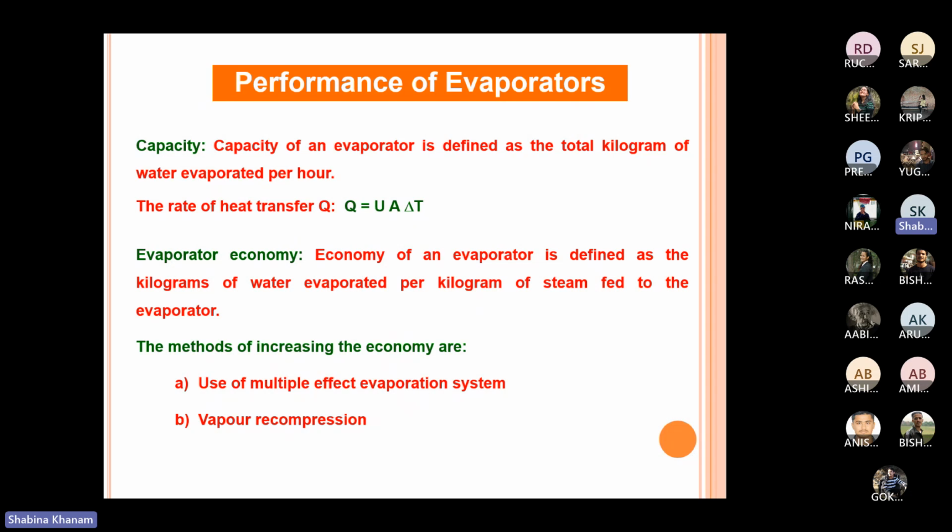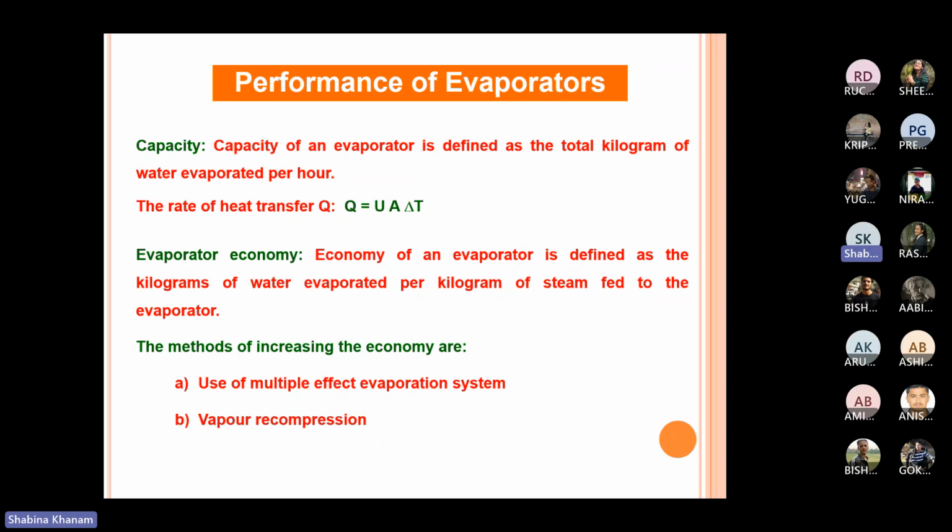Next, if I have vapor in the first effect that is used as a heating media in the second effect, the condensate will also exit from the second effect from that vapor. That vapor must have a certain amount of impurities that may be obtained by entrainment in the first effect, because through vapor some particles may come, so it would not be as pure as the condensate of pure steam. So the condensate of the vapor could be used as a flash, to generate further vapors.